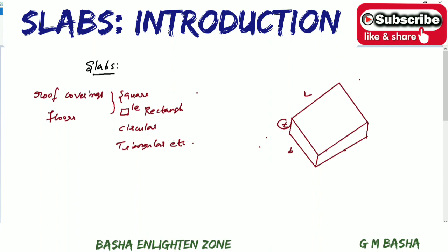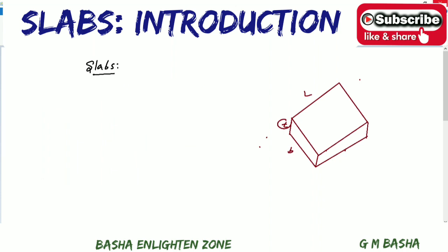According to our syllabus, there will be one-way and two-way slabs. So we will learn the difference between the one-way and two-way slab, and on what condition you will get a one-way slab and a two-way slab. See here. Types of slabs: one-way slab, and the second one is two-way slab. So what is the condition for the one-way slab? Ly by Lx greater than 2.